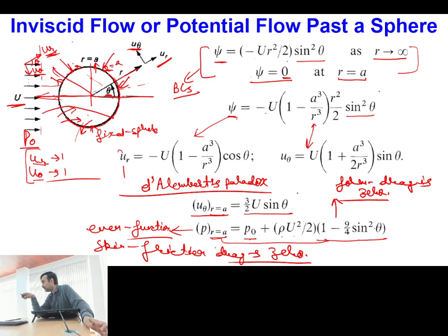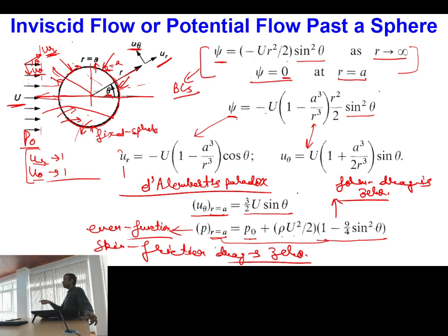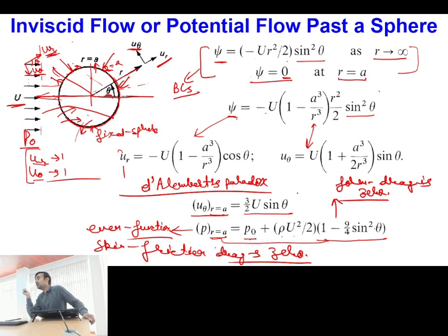And why does that drag come? It comes because of the formation of shock waves, which lead to a discontinuity in the pressure field. On one side of the shock wave we will have higher pressure, on the other side lower pressure, and in that scenario the magnitude of the shock-wave-imposed drag force is extremely high in comparison to the drag because of skin friction. So that actually dominates. That's why for compressible flows, whereas in incompressible flow we say form drag and skin friction drag, we have to consider another component of drag in calculating total drag, which is called wave drag.